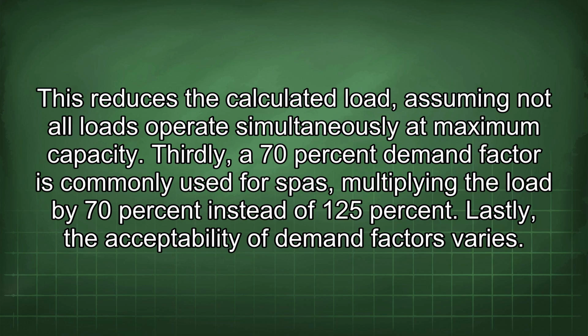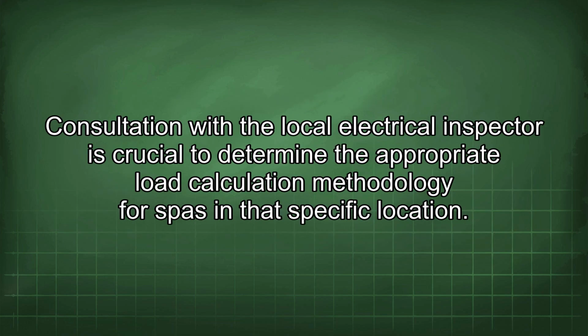Thirdly, a 70% demand factor is commonly used for SPAs, multiplying the load by 70% instead of 125%. Lastly, the acceptability of demand factors varies. Consultation with the local electrical inspector is crucial to determine the appropriate load calculation methodology for SPAs in its specific location.